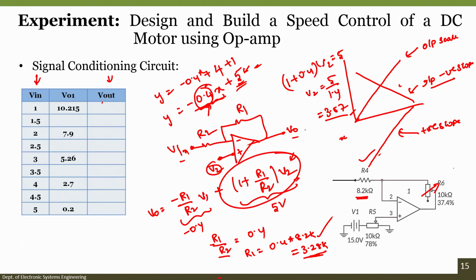Practically there will be a slight variation in the offset as well as the gain that we set here. So, in order to make it realistic, we have considered the input voltage as 15 volts, because all the op amps are powered with 15, so it is very easy to take it. Otherwise, we would have to take another voltage source which should properly match, and instead of providing 3.57 directly, the 15 is connected to a potential divider circuit. So, something like this.